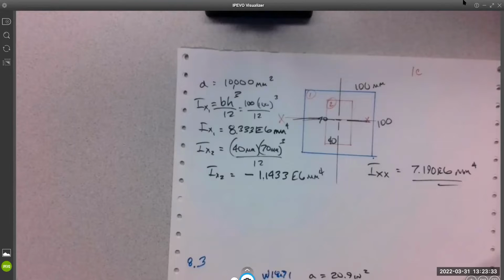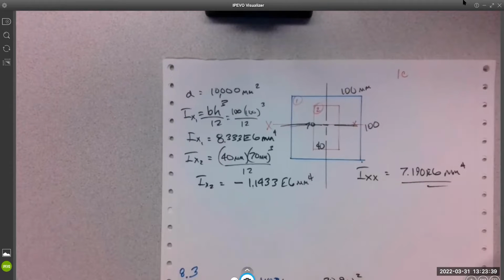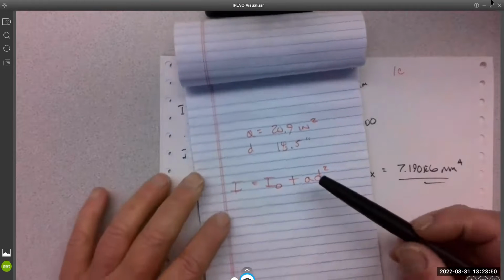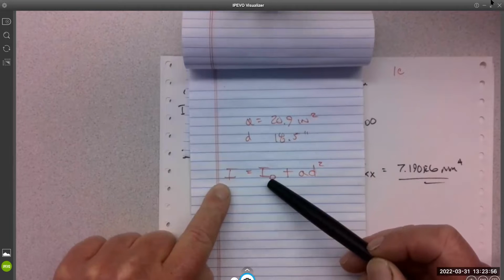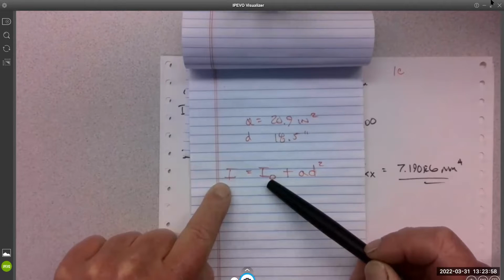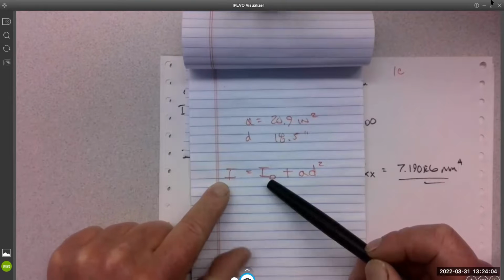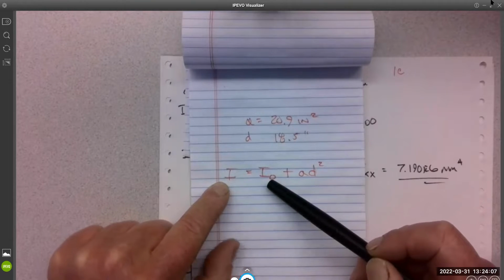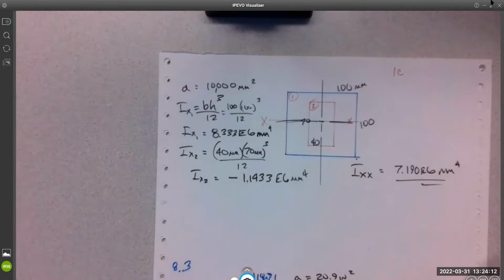Yeah, you're not going to use it. The only thing we're going to use is this. So that's what you're asking. Nope. If they're not in line, we need the individual one. Yeah, because it plugs into the transfer formula, which is this. That's the individual inertia. So we have to have that number to put into this formula. Does that make sense? You could. Yep. As long as it's in inches to the 4th or millimeters to the 4th, then yeah.